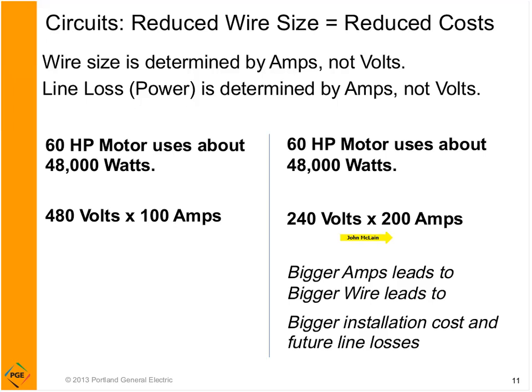This would be the equivalent of in your home, you have a 200 amp capacity panel in your garage. That's code for any new home, 200 amps, but if you wanted to exceed that, you'd have to replace that whole panel if you wanted to put in special extra equipment that pushed you over that. So buying the 480 volt motor might save you a lot on installation costs. So watch out for the amps. It can be a very important measurement and decision-making part of construction projects.